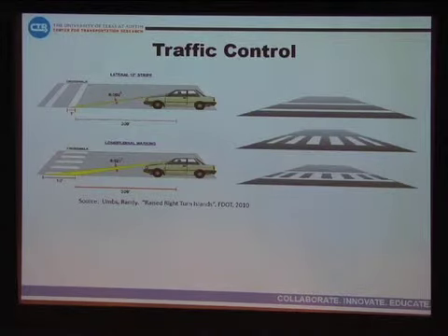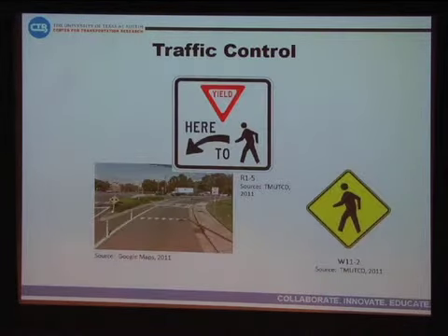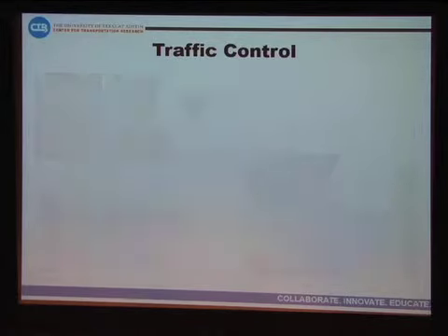they cross the roadway. In terms of the longitudinal markings, those have been suggested as a supplement to be provided at these crossings for their benefit in terms of visibility on behalf of approaching motorists, so they're easier to see than the transverse markings. In addition, we have other supplemental devices that can be used, including additional pavement markings such as yield lines, additional signing at these locations as well.